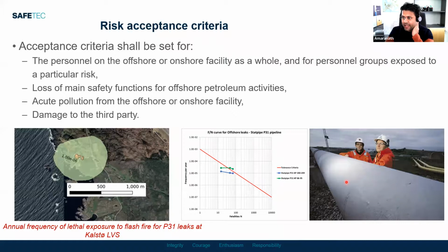And at the areas where you have crossings, for example, if you have a pipeline that crosses over this pipeline, then you have to have some buried sections. Again, if there are areas where you have ship fairways or areas with high shipping activities, then it's very important to have some rock dumping or other mechanisms to prevent damage to the pipeline.